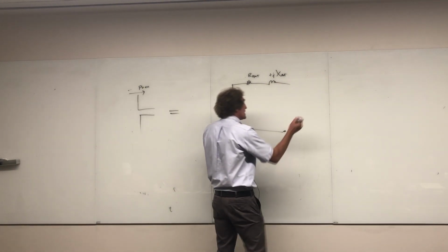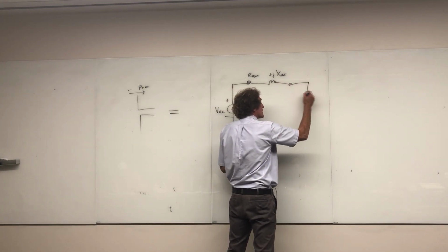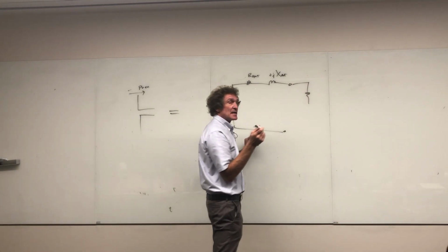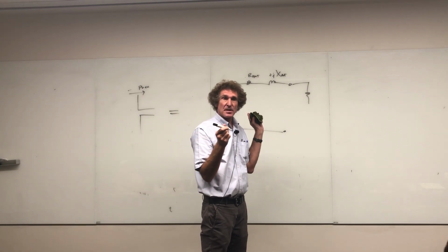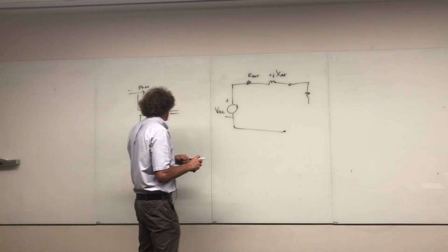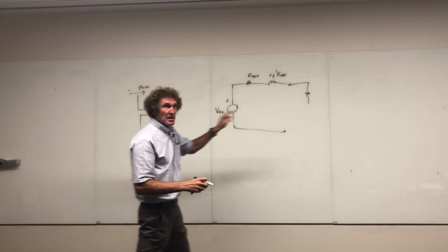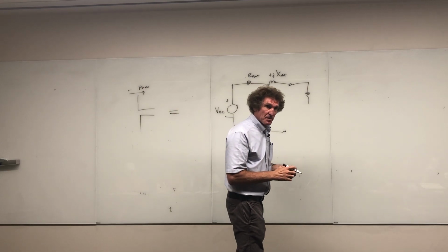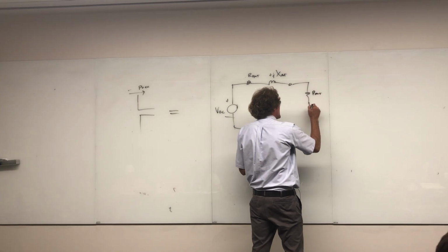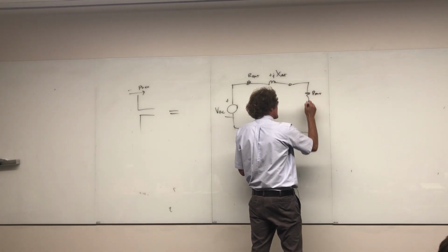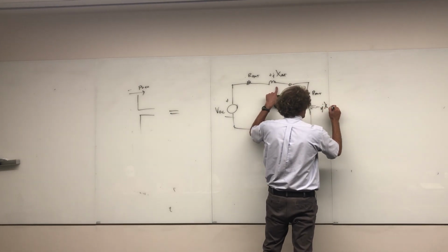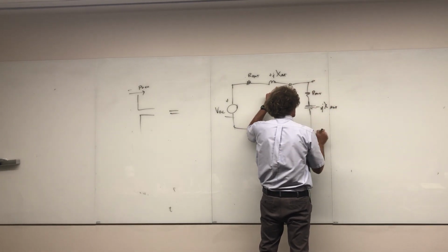There's your antenna. Now out here, you're going to hook up a load. And this is the thing: when the load is equal to the conjugate of the antenna's impedance, you get maximum power transfer. This equation, where I get P received, is assuming a matched load. They don't say that, but it is. So the matched load would have the same R antenna, but then it would actually be a capacitor there. It would have minus jX antenna here. And this is the load. This is the observable load.